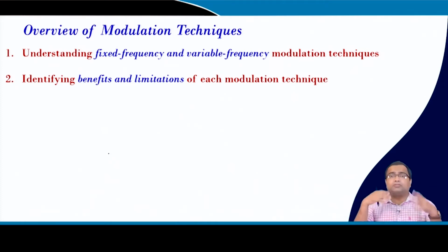Then we have also understood that variable frequency control such as constant on time, constant off time, even for voltage mode, can be much faster than traditional voltage mode control. Also in current mode control, the variable frequency current loop actually makes sure the current loop is inherently stable for the entire operating range.